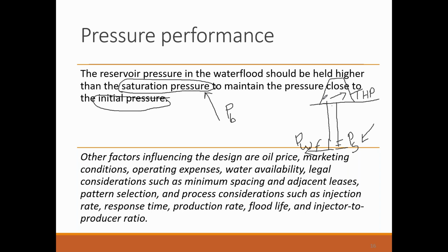you need to be a little bit cautious, because in Oil India Limited, what we adopt is we have two different kinds of wellheads: the rating of one wellhead is around 5000 psi and the other is 10,000 psi. So if your tubing head pressure suggests that the pressure is close to the rating, you need to replace it, otherwise the well is unsafe. This is a bit out of context, but I have noticed this quite often.